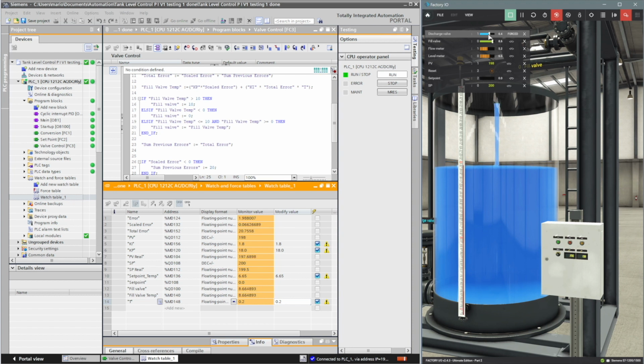However, if you require to change the set point value during operation, then you really should recalculate the variables again for Kp, Ki and T using the Ziegler-Nichols method. You could also modify the code to include an if statement to select the appropriate values for these variables based on the value required for the set point.